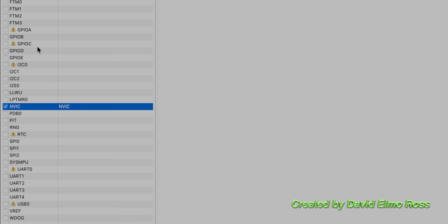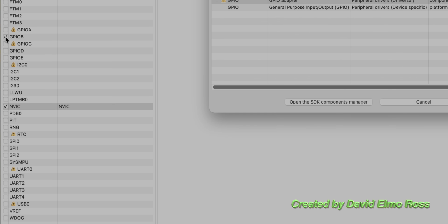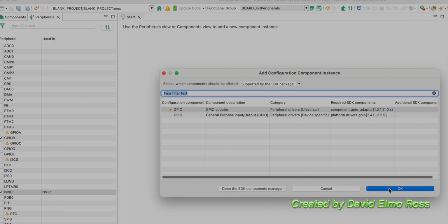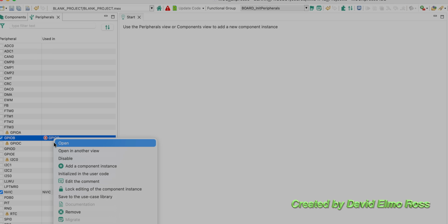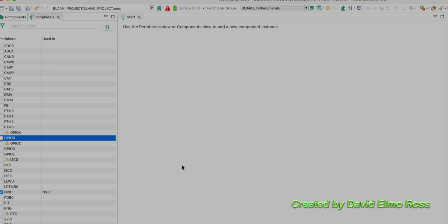We have a way by going through this to actually use some of our GPIOs. We can go here, click on GPIO, we can say OK, and then it's going to allow us to configure it and do things here, or we can actually just get out of here and we can say remove, and when we say yes, it's just back to where it was. So we can actually configure these in this utility here, which is pretty cool.